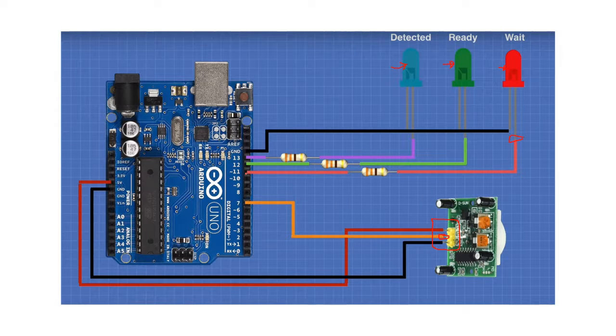And remember, I said all the pins are emitting 5 volts. It's not very sure how big that can be, but an LED cannot receive 5 volts. 5 volts from the Arduino can automatically burn them or destroy them or short circuit them. Sometimes you may want to adjust whichever language you are using, it depends on each subject. If you are a physics student, you can give it a physical or technical term. So for those students who are not taking some of those technical subjects geared towards electricity, you can just say this one would destroy it. And that's why we need a resistor.